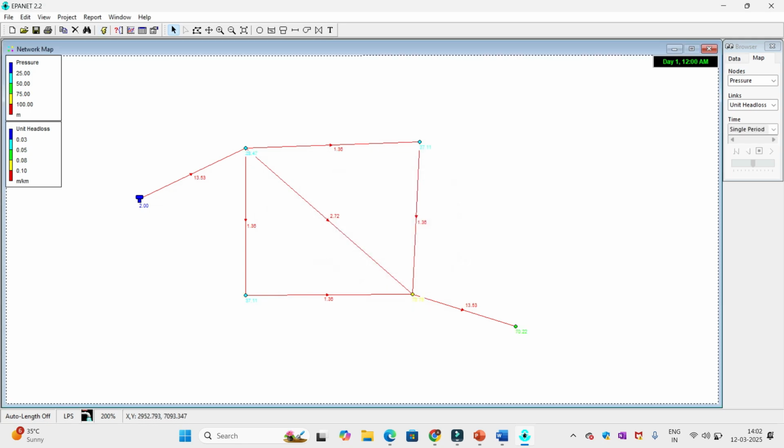Okay, the run was successful. Now it's better, I guess. We can supply our demand at this particular point with a 75 diameter also. And so this is how you can actually simulate simple pipe networks. And there is actually more to this, which I will be discussing in upcoming video lectures. So I will make this lecture short so you can go back and practice. And when you are back and confident with this, we will head to the next part of learning this software.